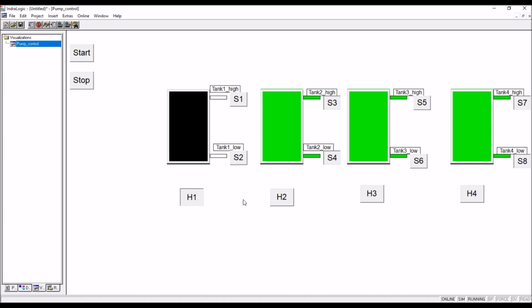Okay. Now tank 1 is empty. And switch off this drain. Now, see, according to the control, tank 1 was empty, all other tanks are full. So tank 1 pump load is only 3 kilowatt, that is under 10 kilowatt. So according to the program, it is filled. As soon as it is empty, it is filled. So that is automatic control. Correct, right?